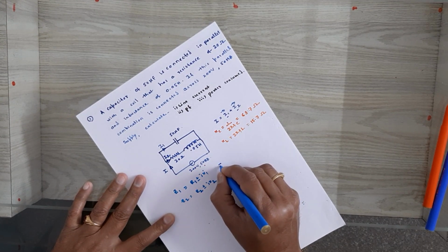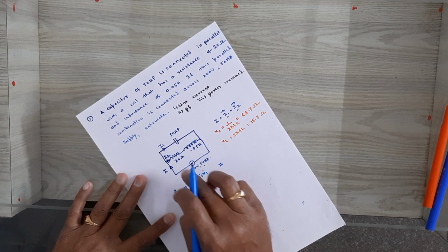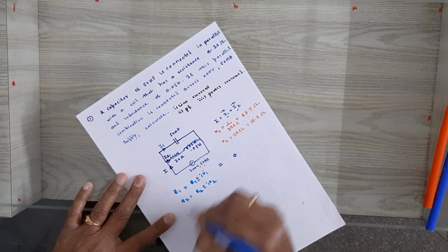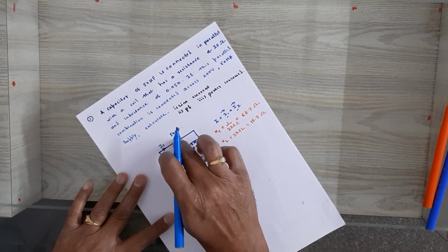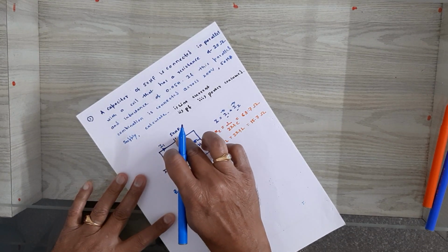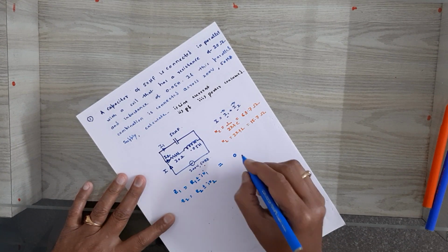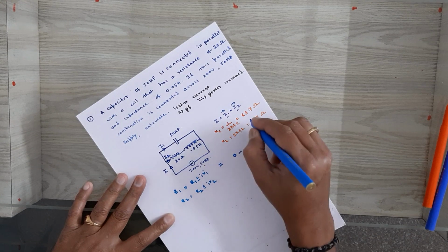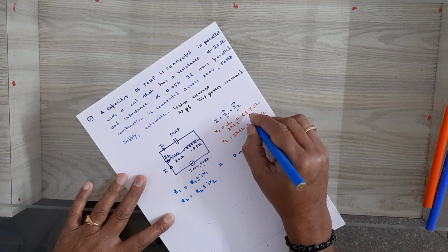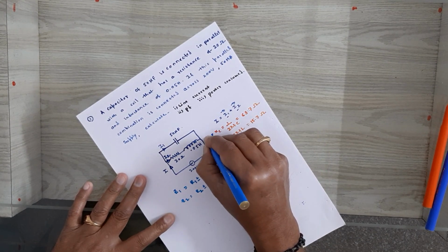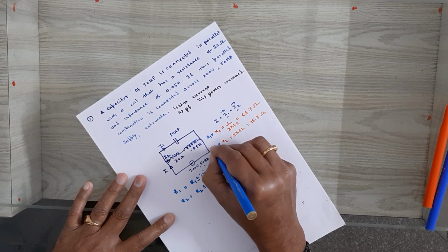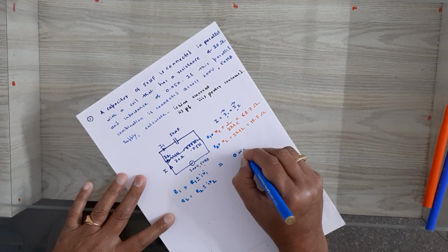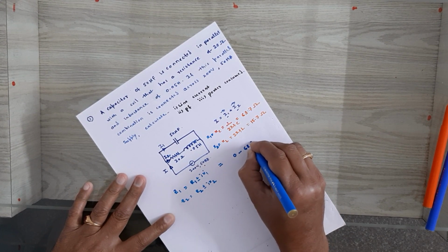For this particular problem, what is R1, the resistance in the first branch? It is not there. Therefore, you can put that as 0. Then what is the type of reactance here? It is capacitive reactance, therefore you have to take it as negative. Therefore minus, what is Xc or X1? This is your X1, this is your X2. That is 0 minus 63.7.